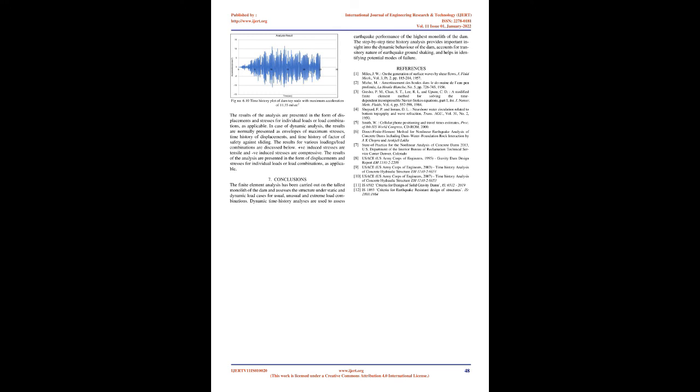Dynamic time history analyses are used to assess earthquake performance of the highest monolith of the dam. The step-by-step time history analysis provides important insight into the dynamic behavior of the dam, accounts for transitory nature of earthquake ground shaking, and helps in identifying potential modes of failure.